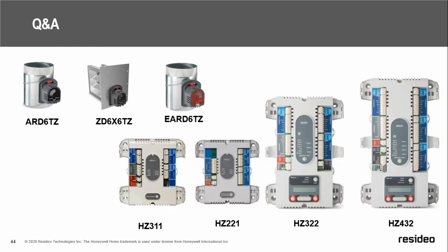You'll be able to see what kind of input is coming in from your thermostats in that LCD display on the 322 and the 432 zoning board, and bypass all the time delays, and you only have to contend with the time delays that are built into the equipment.